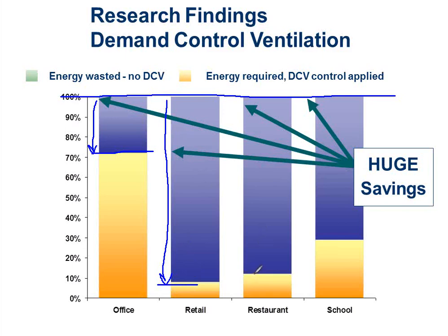Restaurants are similar. They're designed for a peak day, and it's probably the Saturday night dinner crowd, right? But there's less people there on Wednesday night. There's certainly less people there on Wednesday at 2:30 in the afternoon, right? So I've got all these valleys in the restaurant when I'm not at peak design, and I don't have to bring in peak airflow when that's not happening.